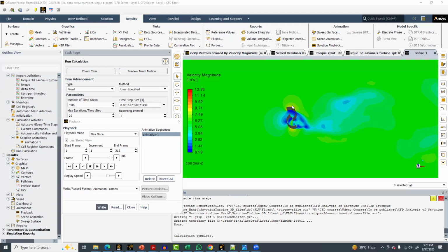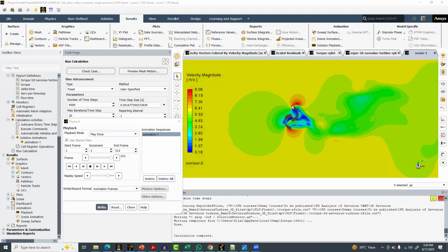Sliding mesh would again be circular motion, with two domains, one rotating and one fixed. But at that time, we use the dynamic meshing, which is used for wall motion and some irregular motions.